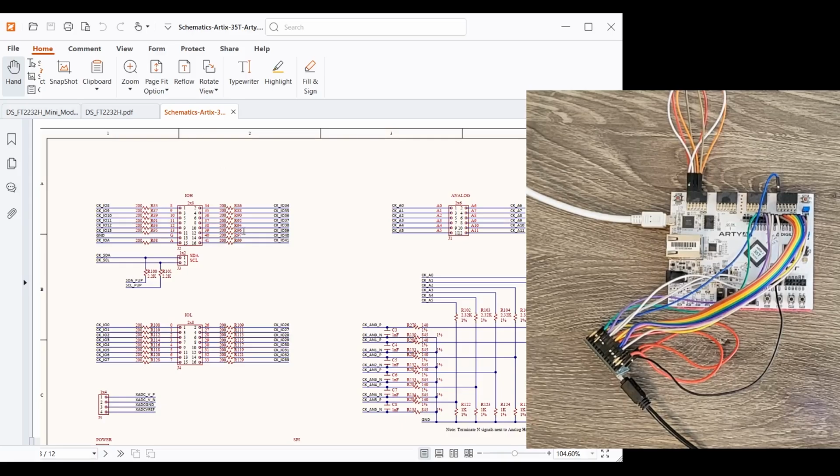And then what I did was I also downloaded the Artix-7 35T datasheet or the schematic. And basically, from the schematic, I found the pins that are available in the board. And I use those to connect the FT2232 to FPGA. This is, of course, not the best connection, because these are 60 megahertz signals, and definitely this wiring is not optimal. But so far, I was able to make this prototype with them, and eventually, once everything is finalized, the plan is we put all these into one PCB and optimize the wirings.